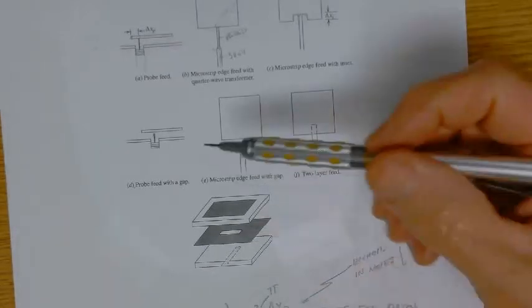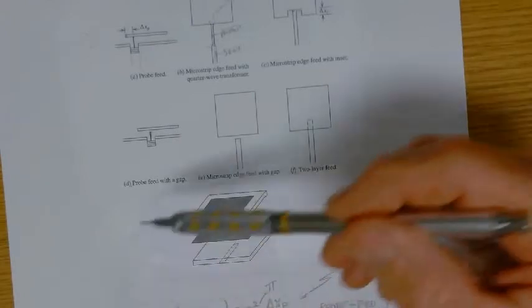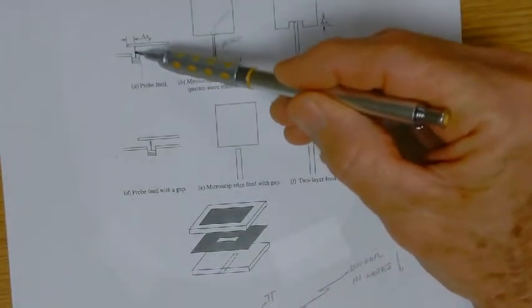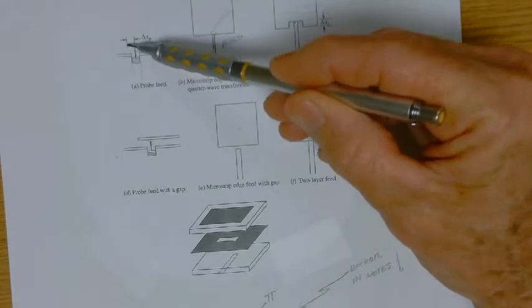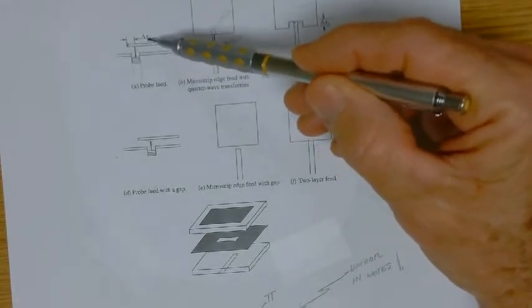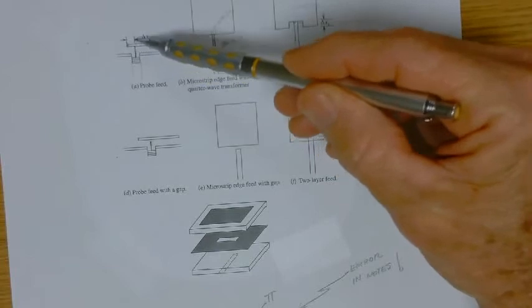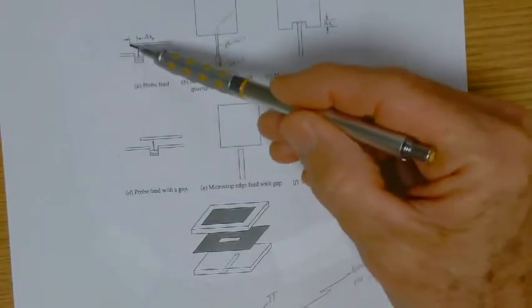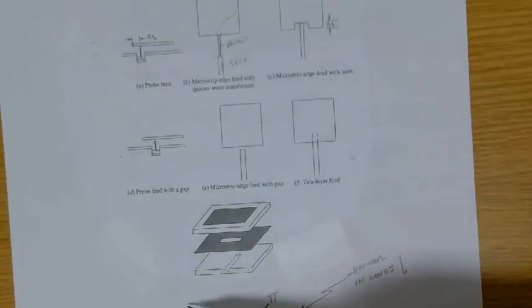Okay, so again, what's the issue? The issue is what is the input impedance when the probe is moved over, and you're feeding not at the edge, but into the patch a distance delta x of p. It's the input impedance that you would see if you fed it at the edge, this number, times cosine squared of pi delta x of p over L. So we say the input impedance changes like the cosine squared of this quantity.